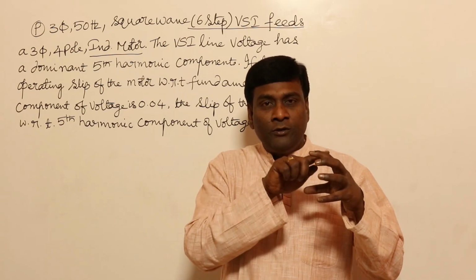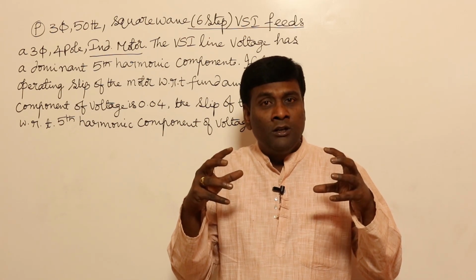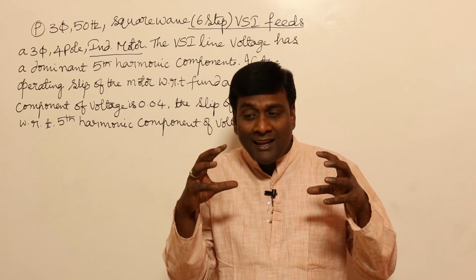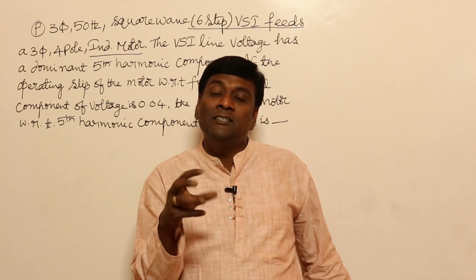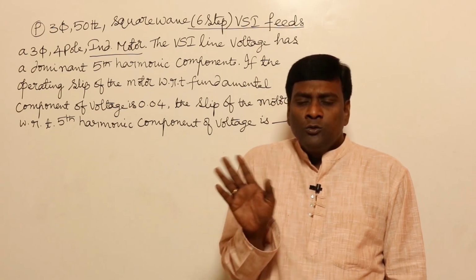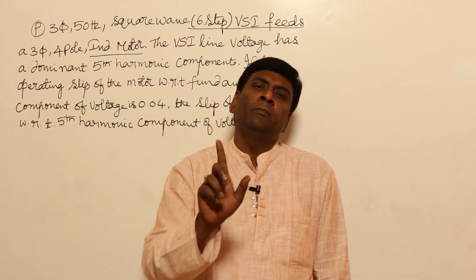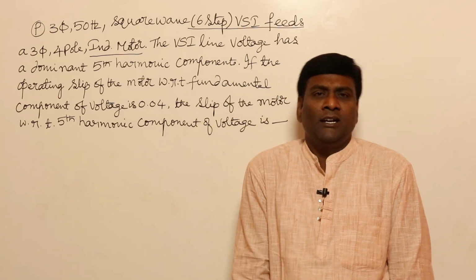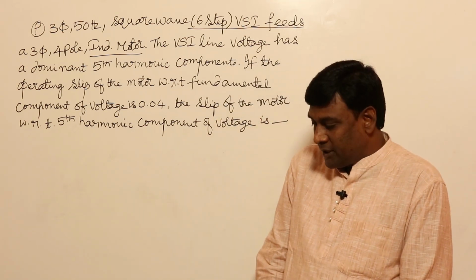Now, if load is increased on this particular generator, prime mover speed will be reduced. If you want to analyze this prime mover speed reduction, you have to remove the generator and analyze the mechanical prime mover. Is it required for us? No. So normally in all generators, prime mover speed regulation is not considered and speed is assumed to be constant. But only in one case are we going to consider speed regulation of the prime mover.